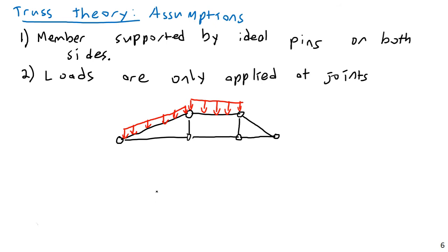But anyway, I'm coming back to these things being impossible. Just because an assumption or a model is impossible doesn't mean that the idealized case cannot be useful for design. This is one of the reasons we have things like factors of safety and LRFD. One of the reasons for that is to take into account the slight differences between our idealized model and the real world situation. But you need to make sure to use the correct model, because if you are using an incorrect model, your modest factors of safety won't take care of that. We might design things twice as strong as they need to be in some extreme cases, but we very rarely design things 10 times as strong as they need to be.